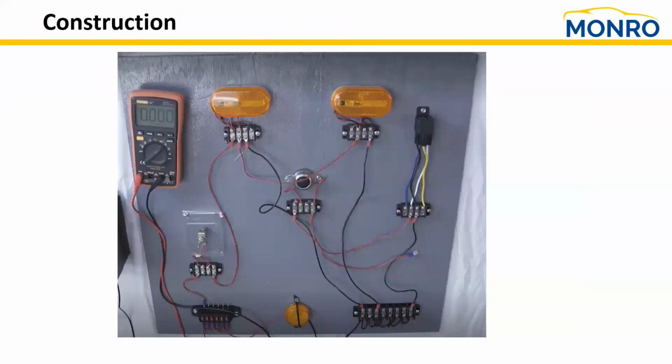We take that same circuit board and we have battery positive power. We run the battery positive power the same way through the switch. In this case, we run it up to the load, and from the load, we ground that first load, causing that one to light. Now we go back to battery negative. Now let's go to the second one. We see a splice at the first load that's now traveling over to load number two. And again, load number two has its own ground, or its own path back to battery negative. So that's how the circuit was constructed.